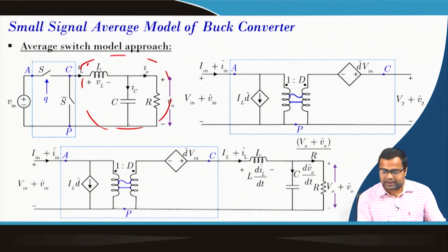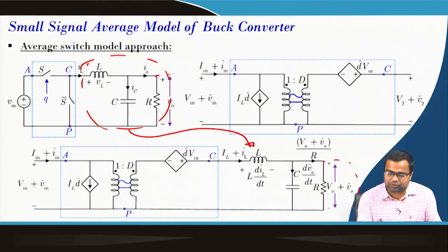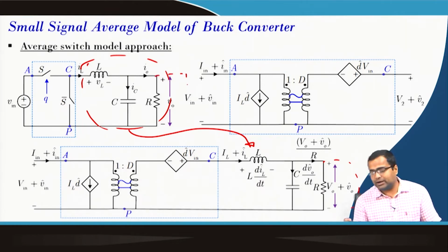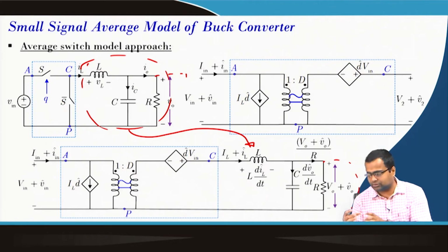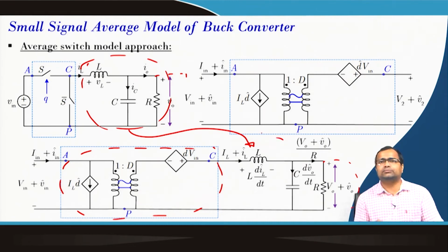So, this part now we can join back, and the beautiful thing is, if you incorporate a current load, you can also incorporate it here. If you incorporate the additional impedance or the filter element, the same model remains; we will not touch this part as long as you do not change anything. Then we can update the right side of the switch model without rewriting the equations, and that is somewhat special in this technique compared to state space averaging, where we need to rewrite all the equations every time we add any dynamic element.